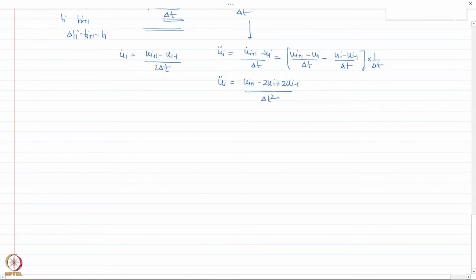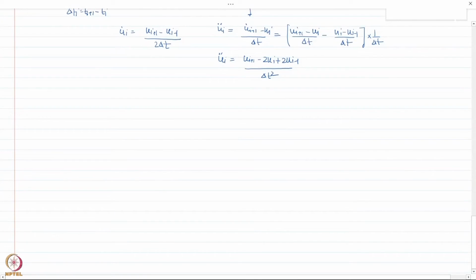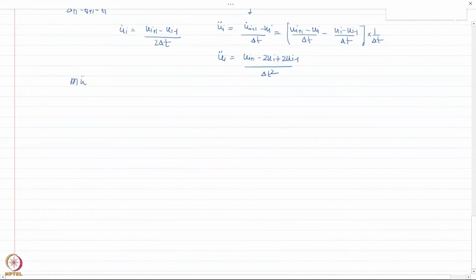So what I have done here is written down my velocity and acceleration, which are time derivatives of the displacement, simply as expressions of displacement. Why is it necessary? Well, in the differential equation that I have, all the derivative terms can be removed if I substitute these and write it in terms of only displacements. And that becomes very useful to us. Why? We will see now.